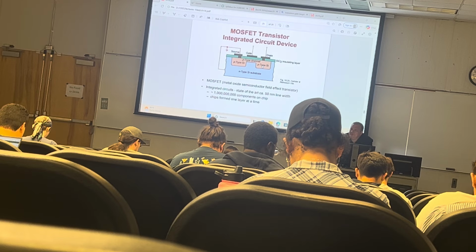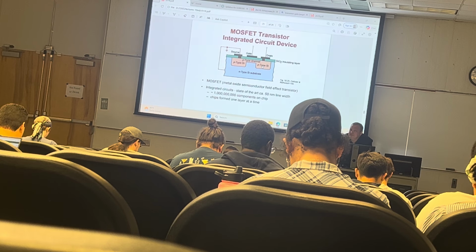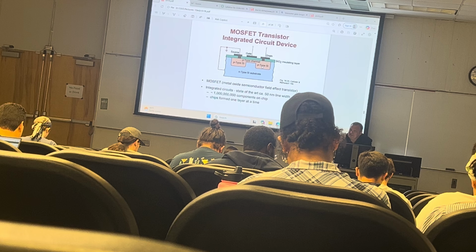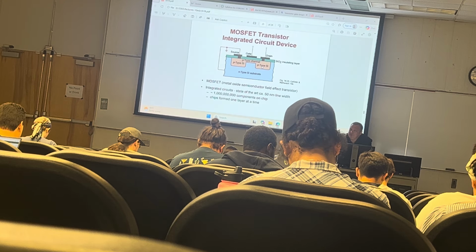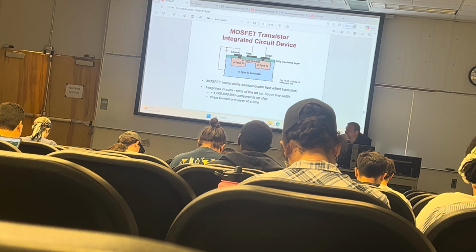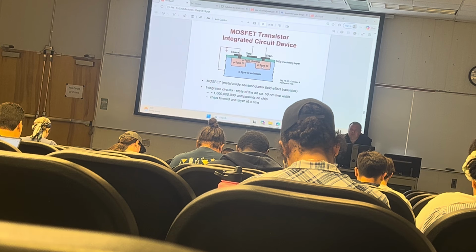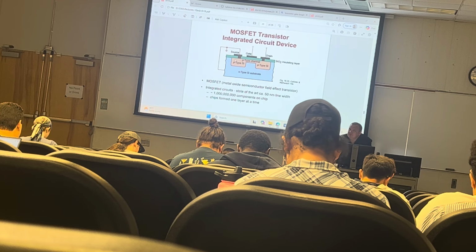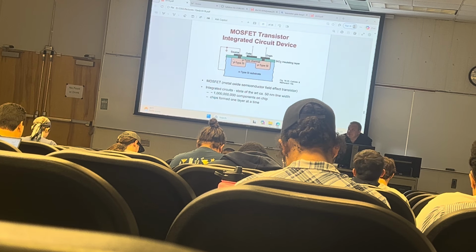There's a photolithographic mask that uses photoresist. So there's a layer of this photoresist that is sensitive to the UV, or now there's UV, but before just regular light. That gets cured. Without getting into too much detail, it's kind of related to the old type of photography. And then you have a trench. See, there's a trench? And then through that trench, you can deposit boron.